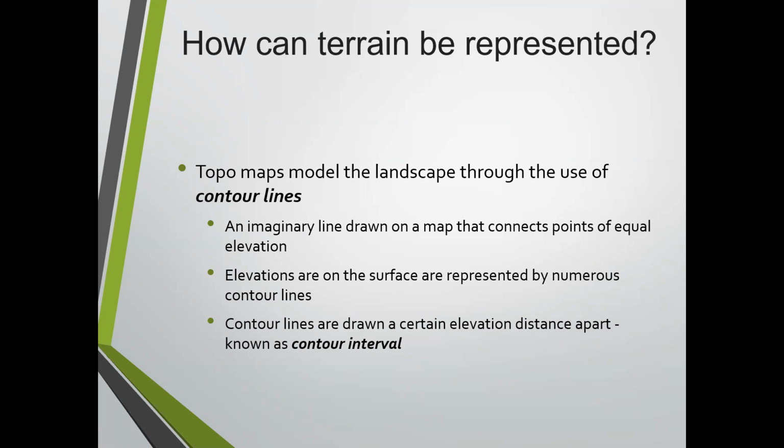And the distance between any 2 lines vertically, that you really can't see, those would be coming at you, is known as your contour interval. So that's the smallest distance that those lines are going to mean in their change. So we'll see that here in a second. But the selection of that contour interval is dependent on typically 2 things, the scale of the map, but also the terrain itself. So you kind of got to look at both.